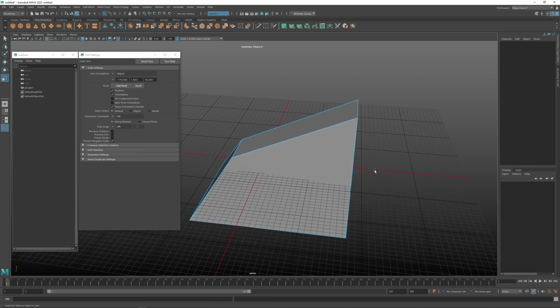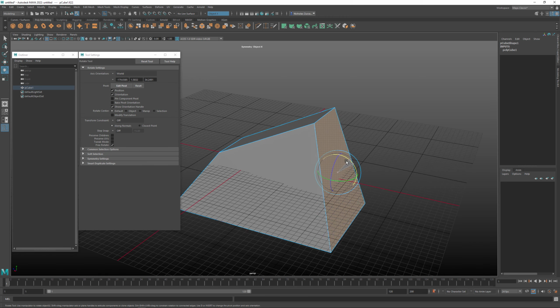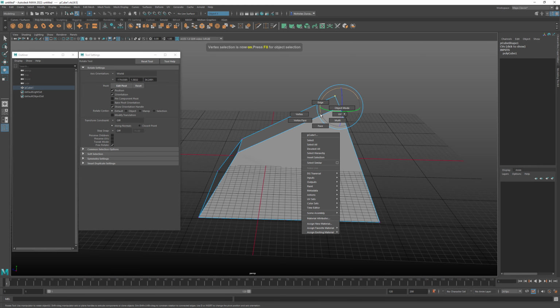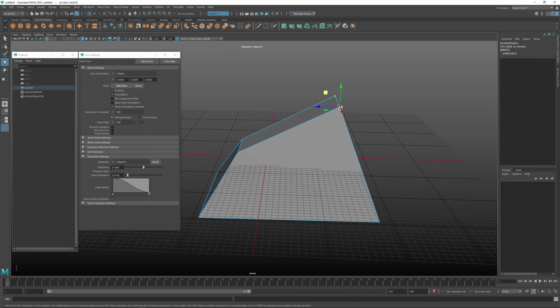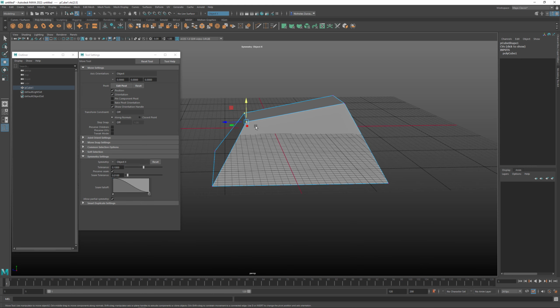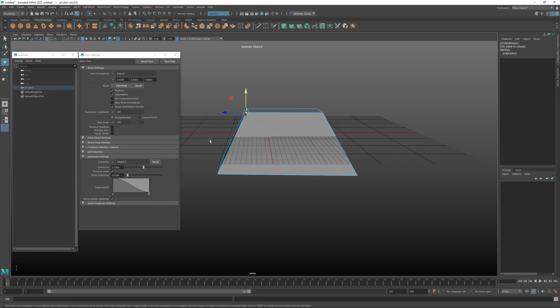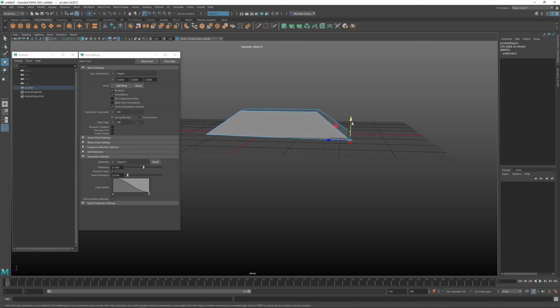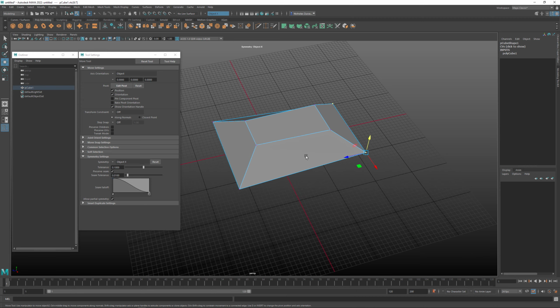And you would have to do something like what I showed you, where you take this and you would rotate this a little bit. So I'm going to go to F9 and I'll go to Verts, or you can right click and say Vertice, and then just move this thing down like this. I'll go ahead and move this up here. I'll take the bottom base of this, hold down X and move that up on the grid. We've got this, hold down X and move this on the grid as well.